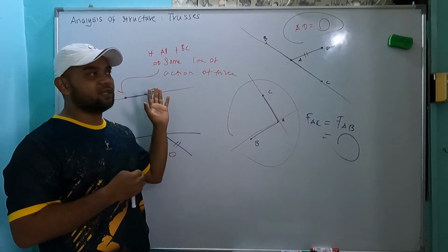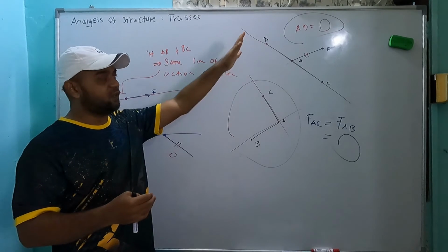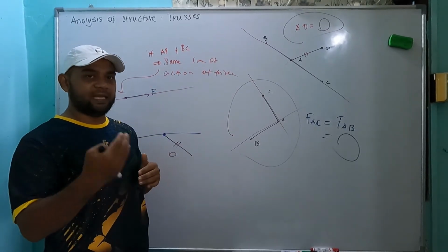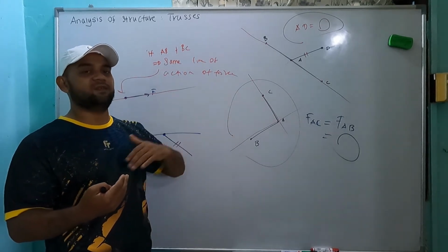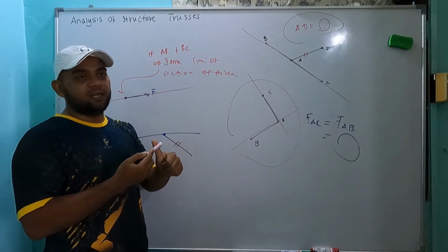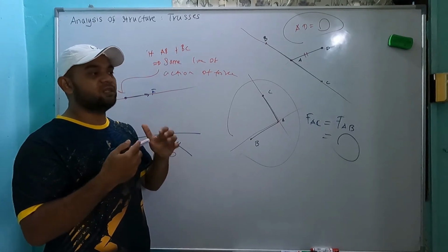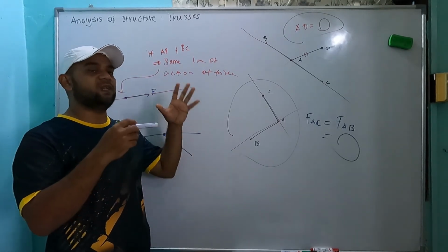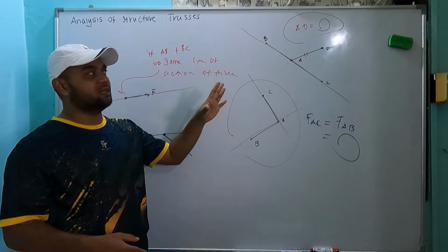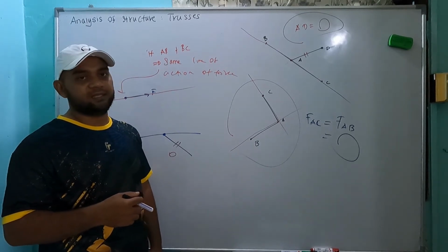Okay, that's why we have trusses. For that specific component only, the force is not there. But if the load comes from a different angle, maybe the component will take action and transfer the force. That's why we will not eliminate the component. First, to cater for different types of loading conditions, and to maintain the structure of the trusses itself. So there are two big reasons why we maintain the zero force member inside the structure itself.